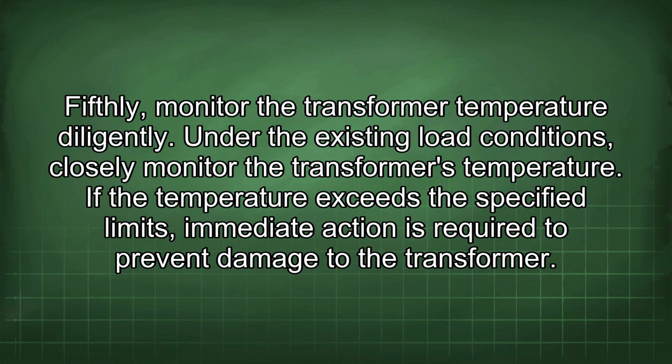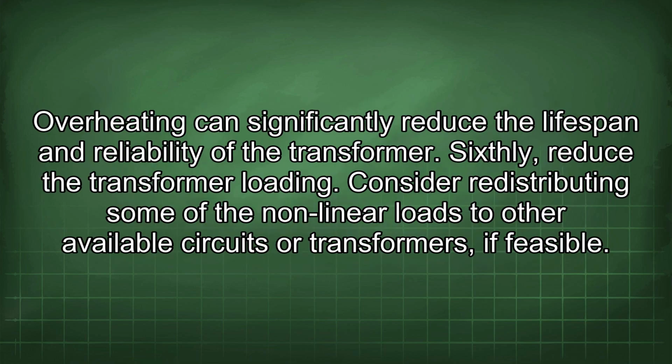Fifthly, monitor the transformer temperature diligently. Under the existing load conditions, closely monitor the transformer's temperature. If the temperature exceeds the specified limits, immediate action is required to prevent damage to the transformer. Overheating can significantly reduce the lifespan and reliability of the transformer.